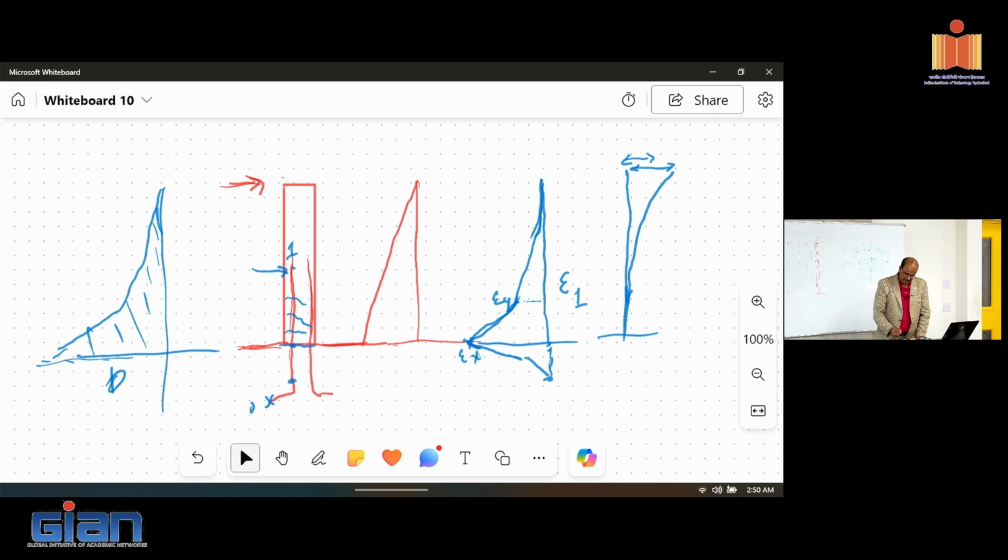Plus what's going to happen here is, your foundation is rigid. Even if they crack locally, you're not going to see anything outside, right? So what happens here is that because the strains are so high, there's going to be strain compatibility between the surrounding concrete and the reinforcement penetrating into the foundation. So some of this region will basically get debonded.